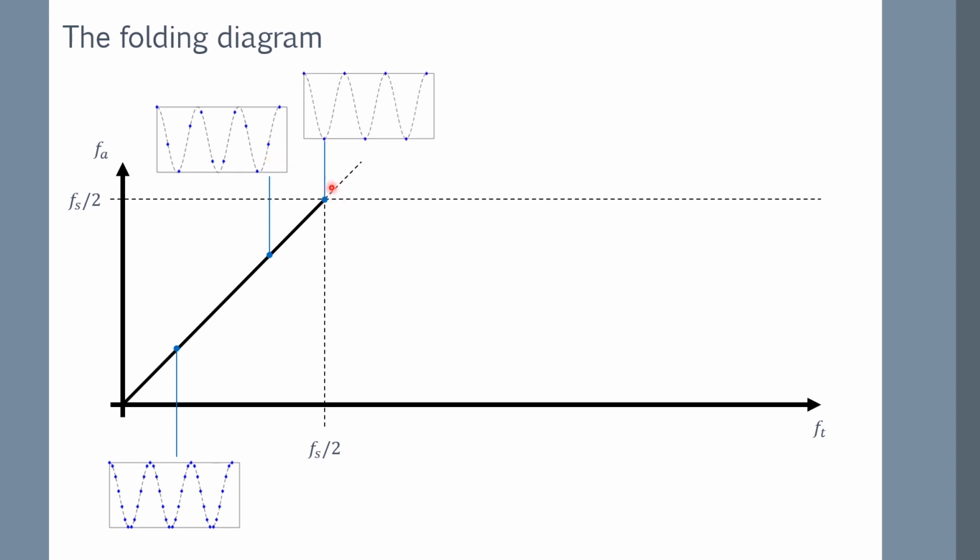If we are here, and this would be the limit, we get 2 samples per cycle. You see the cycle starts here and ends here, so you get this sample and this sample for the first cycle. For the second cycle, you get this sample and this sample. Because we're exactly at half of the sampling frequency, we get exactly 2 samples per cycle, which means that if we connected the dots, we get this triangle wave that is horrible looking compared to the original wave, but still has the correct frequency and the correct information. The amplitude might not be right depending on where the point is that you connect, but it turns out you can prove mathematically that it's still correct in amplitude.